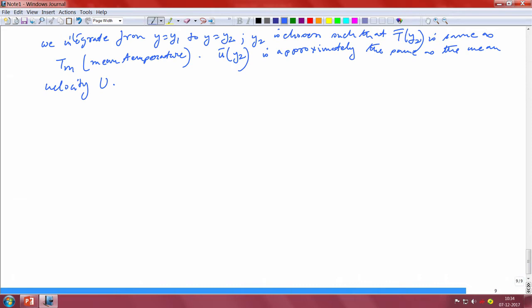Here, of course, we are neglecting gamma and alpha, because epsilon m is greater than both those quantities. So, when you integrate this, it becomes epsilon m by tau naught times u minus u1 bar equal to Cp epsilon h divided by minus q naught double prime times Tm bar minus T1.